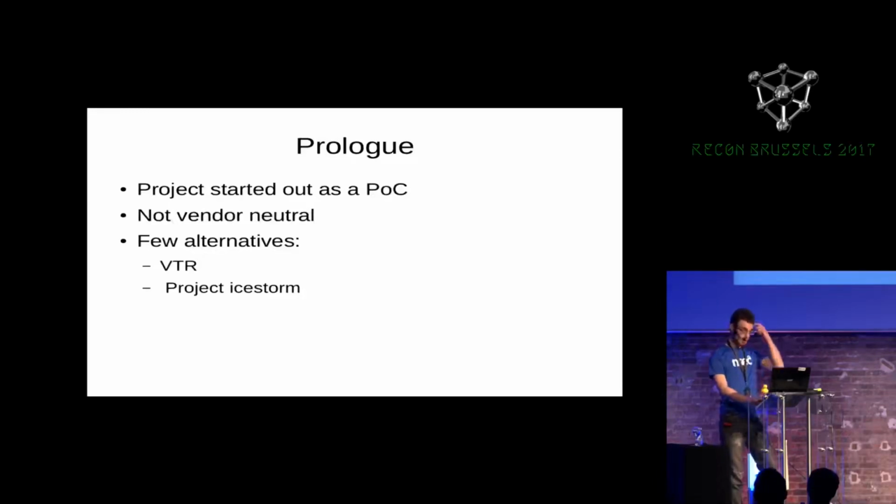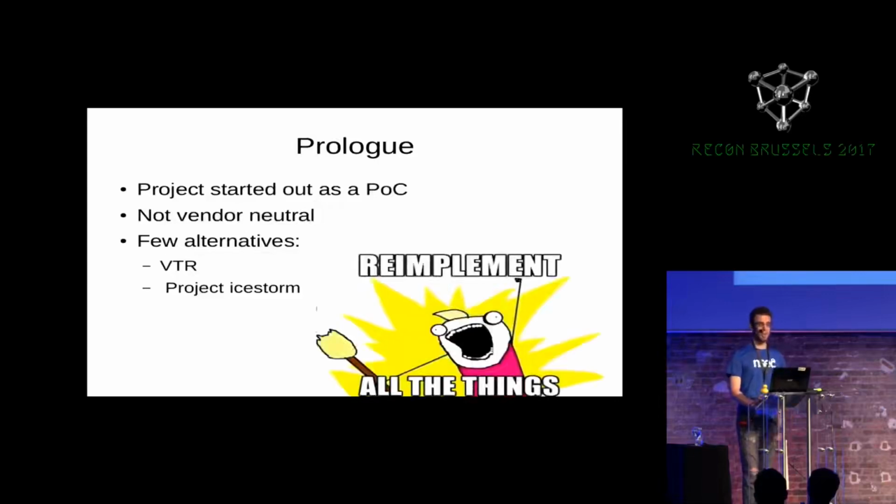But when I looked at Project IceStorm, it's in the middle: before going into an actual bit file, it's a partial bit file. So if you want to analyze that, you're starting off way too deep into the process. So I decided, okay, well, I'm going to go with VTR and re-implement a bitgen.